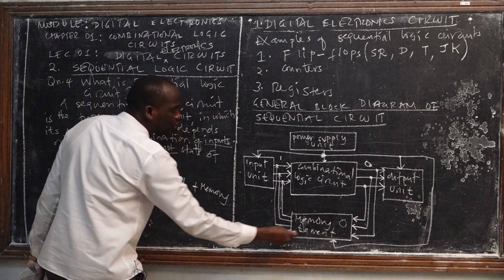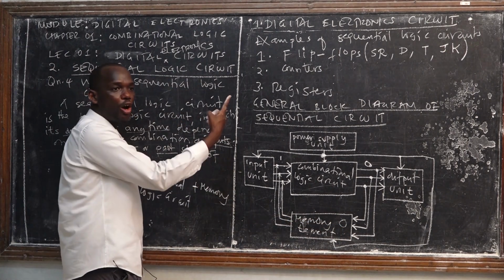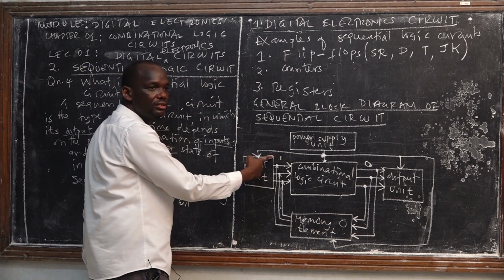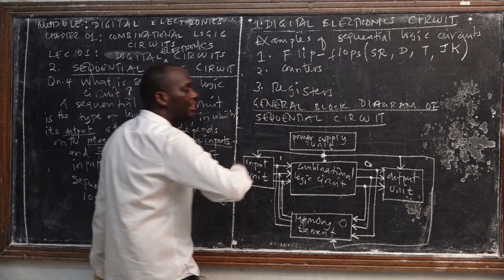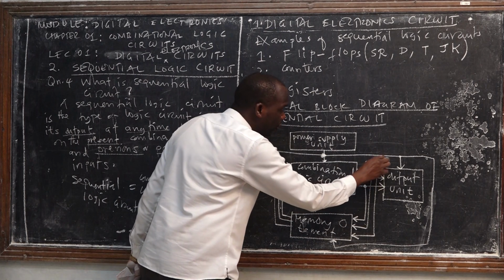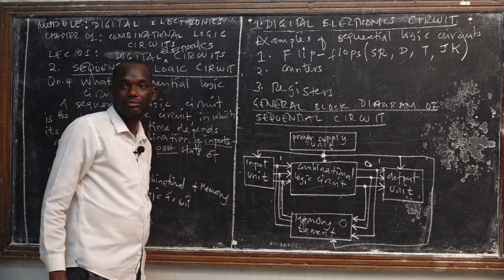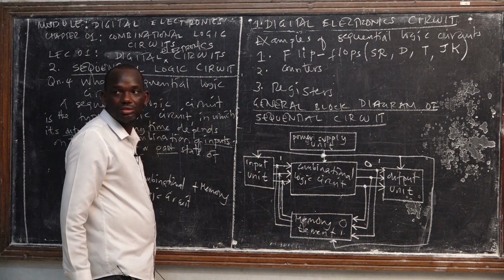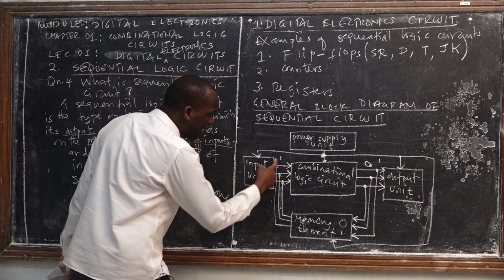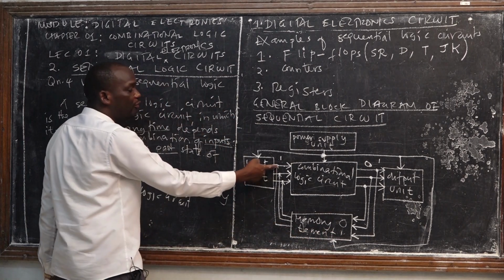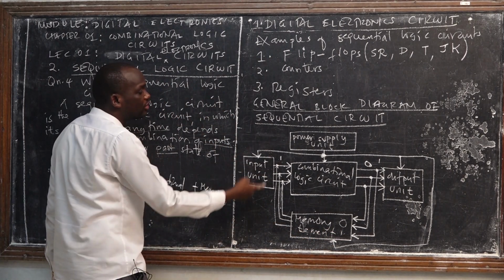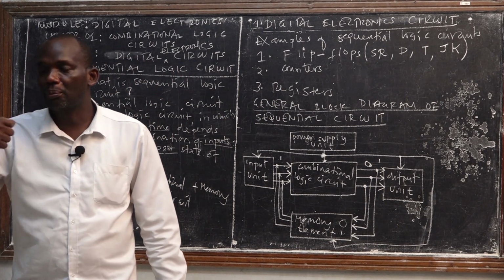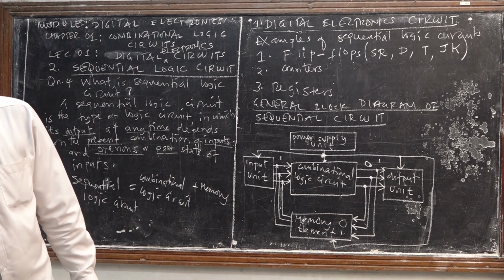These memory elements will bring the previous state of the output, which was 0, and it is combined with 1, and we get another new output, which might be, for instance, 1. This 1 is also taken into the memory, right? For the next combinations, this 1 will be fed in with the inputs and combined with the input to provide the output. That's how the process goes on.